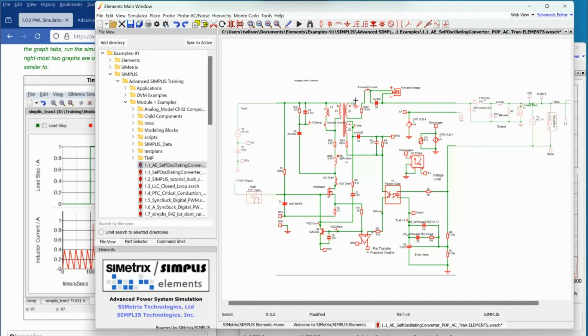Here's the energy storage transformer, with a kind of discrete lumped model. So you can see we have the ideal DC transformer, a nonlinear magnetizing inductance reflected to the primary, winding resistance in each of the windings, and a primary leakage, so reflecting the leakage inductance to the primary winding.